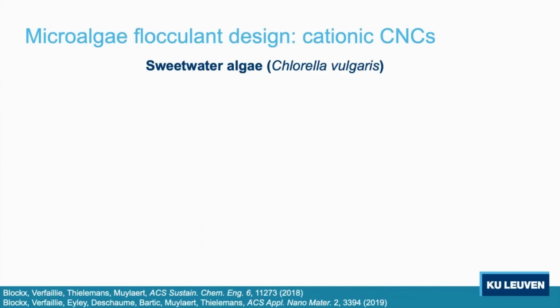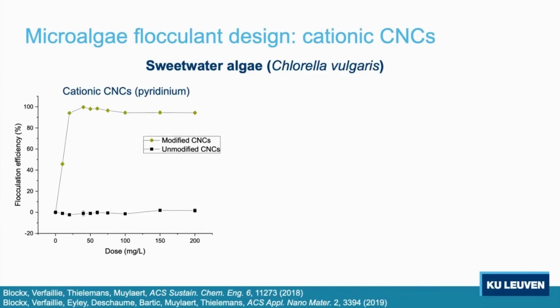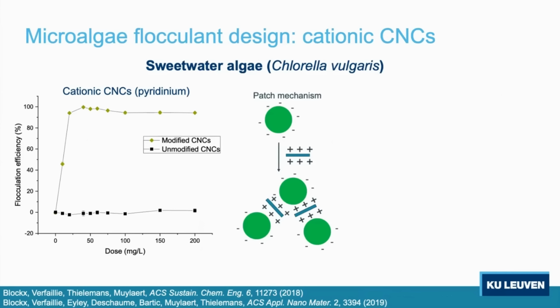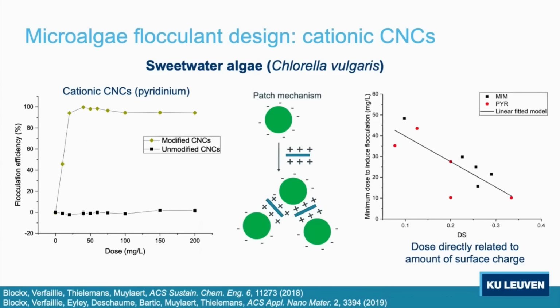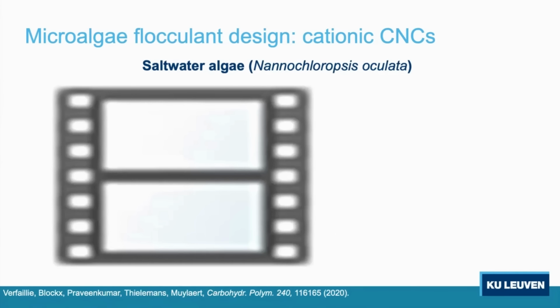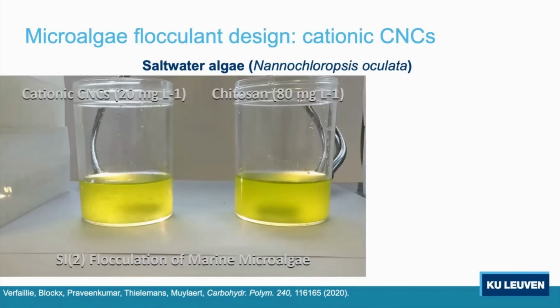And so with sweetwater algae, we see that we get very nice flocculation, 100% with the modified CNCs, and we don't get restabilization. The reason for that is the mechanism, and I'll spare you the details, but we actually proved that it's via a patch mechanism, so you can never get restabilization that way, and the efficiency of flocculation scales with the amount of surface groups you have on the surface. Very interesting is that this also works with marine algae.